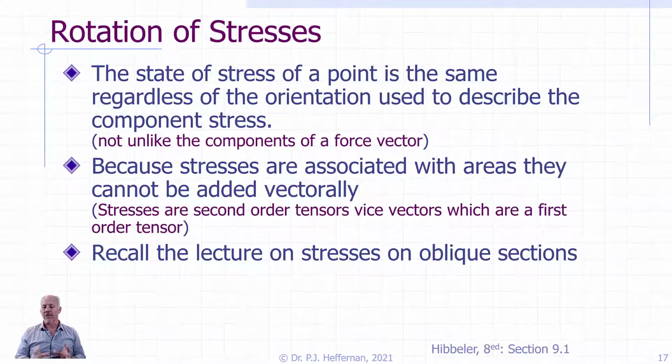And then that is the stress that we're going to need to compare to our material properties to decide if we have an adequate situation, or if we're doing a design, use that stress condition in order to design our part to be able to withstand it. Slightly more complicated than forces. Our stresses, of course, we know as we start changing the orientation, they're also related to the areas which start to change as you change your orientation. And so they don't have that straight vectorial manipulation that we would have with forces.